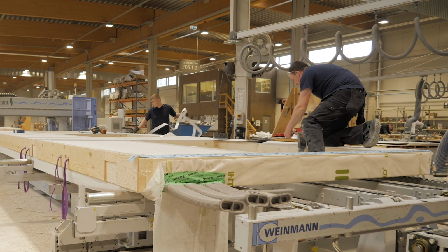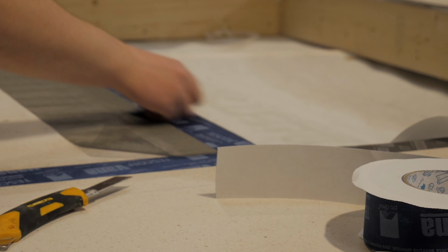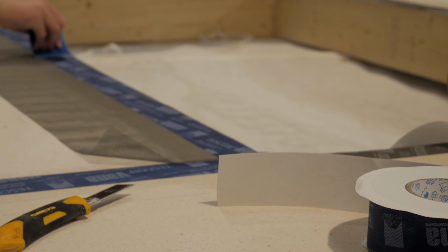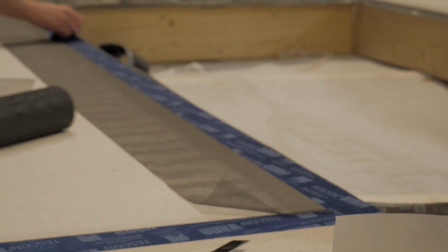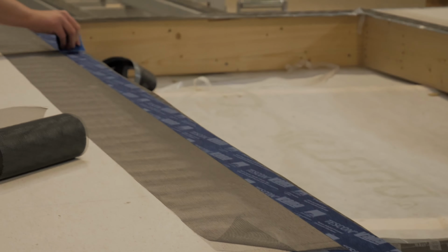The insect net is crucial to prevent insects from entering the construction of the frame. Since the facade covering will be placed on timber laths, the insect net should be secured where air flows behind the lining. Therefore, ensure the frame is air-sealed tightly by securing the tape with a spatula. Before installing the facade, secure the exterior windowsill to prevent water from dripping under the facade.